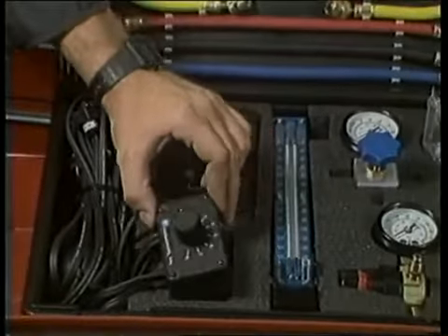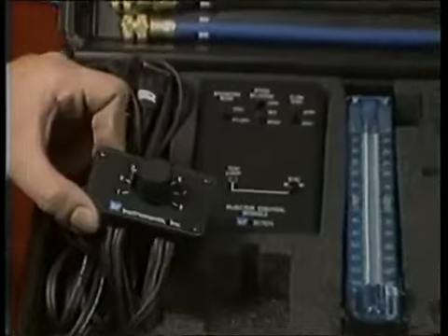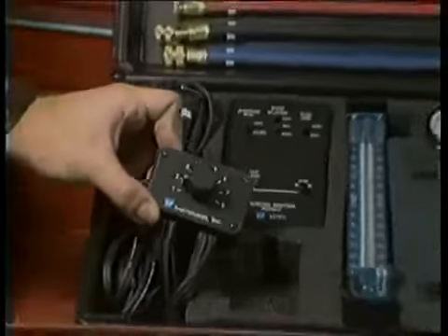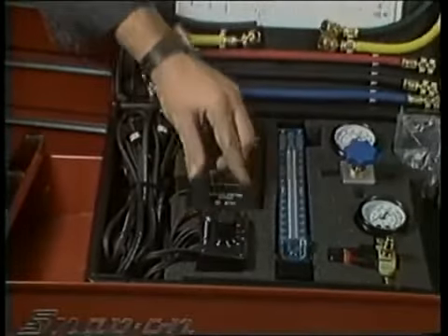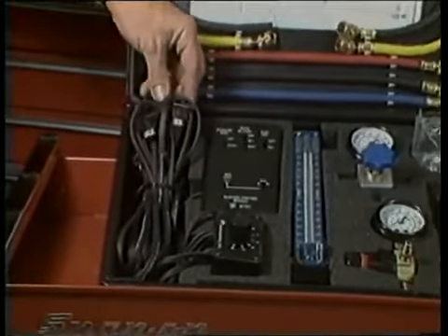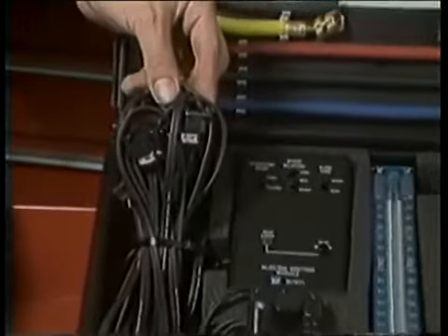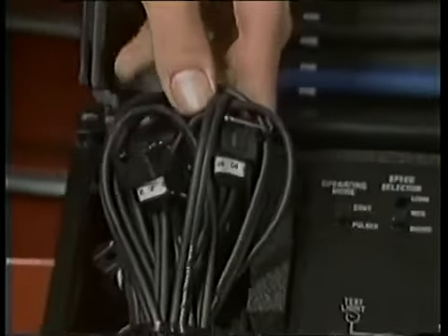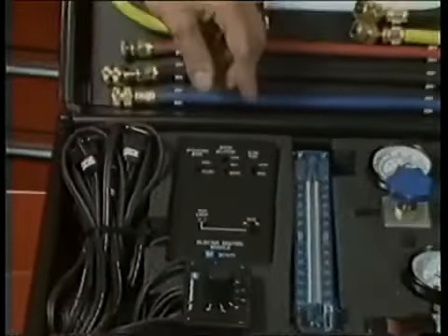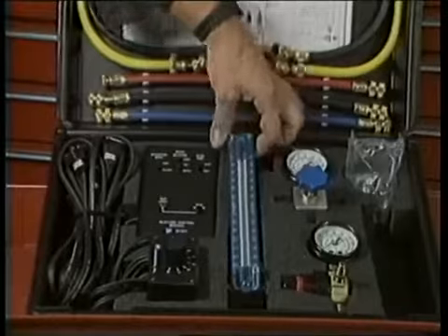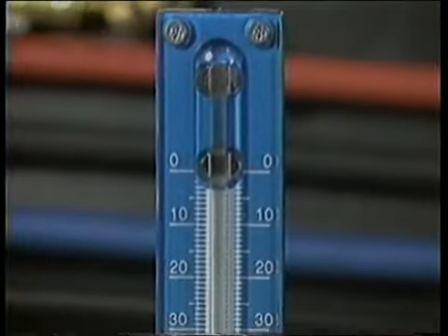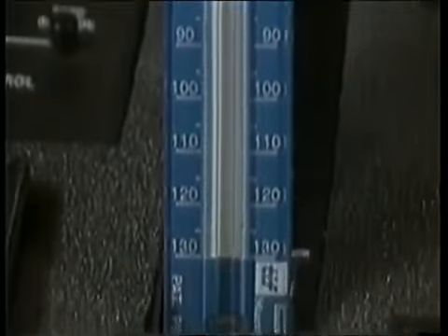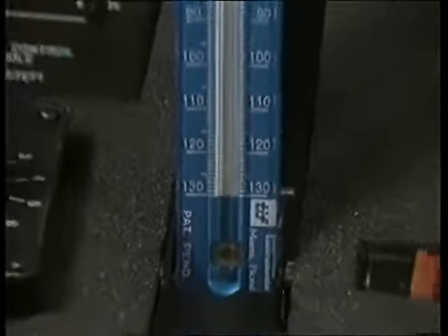An injector selector and harness assembly allows you to select which injector is being tested. The harness connectors will work on most types of electronic fuel injectors. This tester is unique and very accurate because it fires each injector and measures its fuel output. This is a sight glass. It'll be used to measure how much volume of fuel is injected when each injector is triggered electronically.